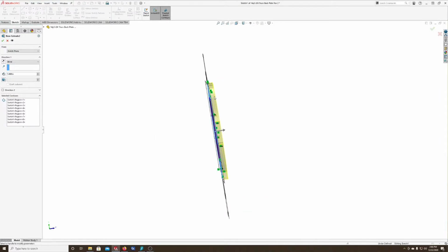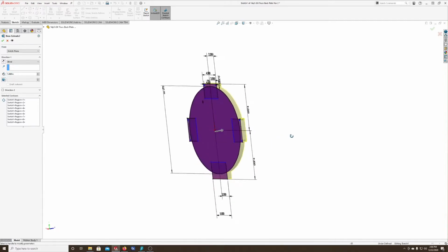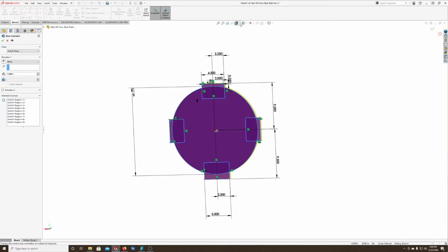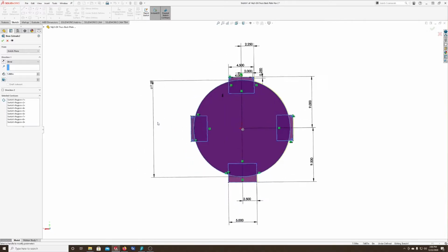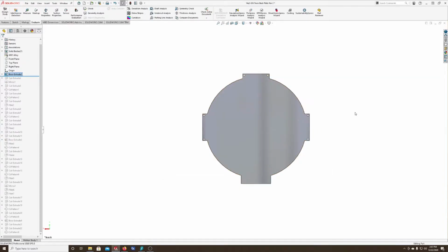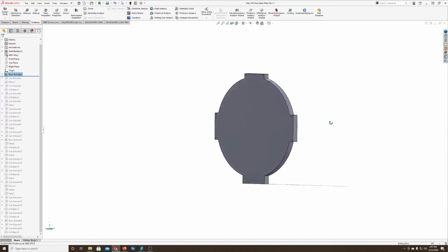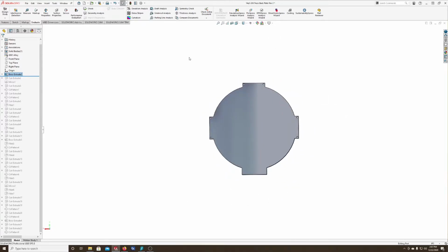This yellow shaded area is a projection of an extrude function, where we'll actually give thickness to the part. Once you have the drawing defined, you can do the extrude function and add thickness. In this case, it's going to be 1 inch. I define the areas of the drawing that I want to be extruded to that 1 inch, and it creates a three-dimensional object with the dimensions and features that I outlined.